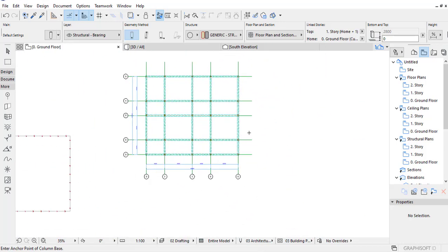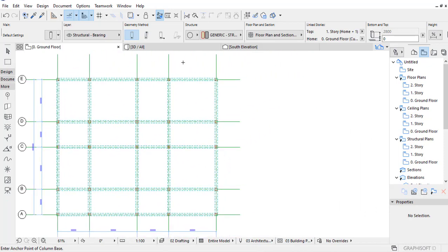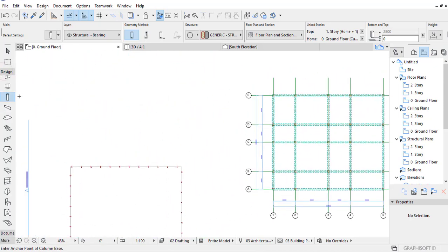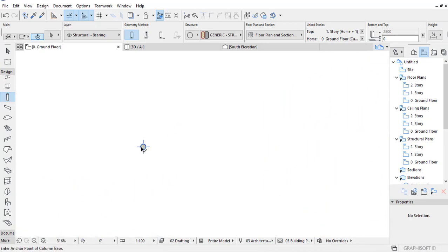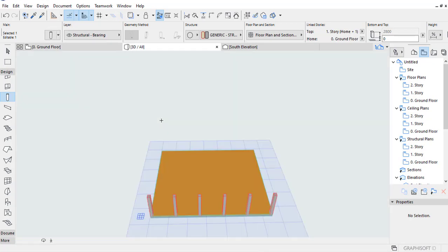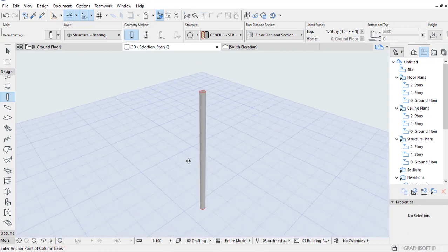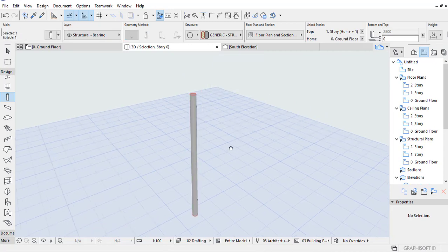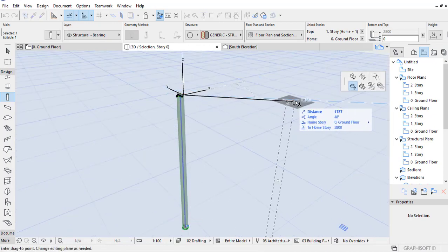You might want to look at the 3D modification options in the 3D for the columns. So you can draw a column here and select on it and press F5. So we are able to look at only that column, one column, and let's use Shift Select and then click on its modification grids. See what options we have.